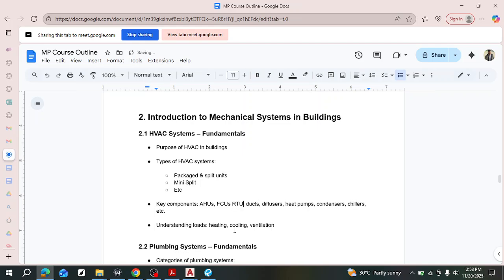So you said air handling is the general type? Not a general name per se. It is just the equipment. That equipment that handles air is called an air handler. There's a separate equipment that handles the heating and cooling. Sometimes an air handler consists of heating and cooling coils, which are connected back to an outdoor equipment where the heating or cooling is done.